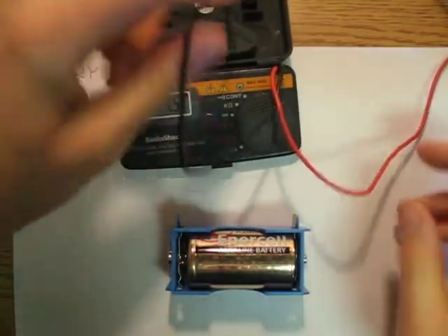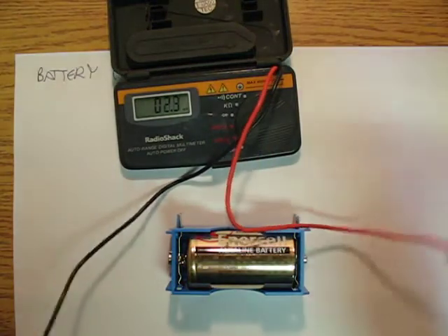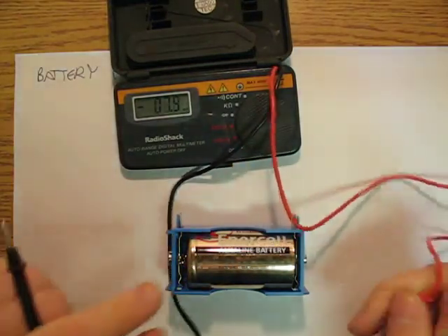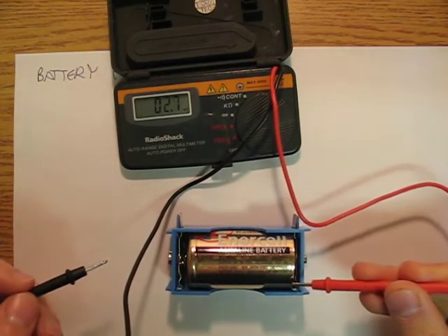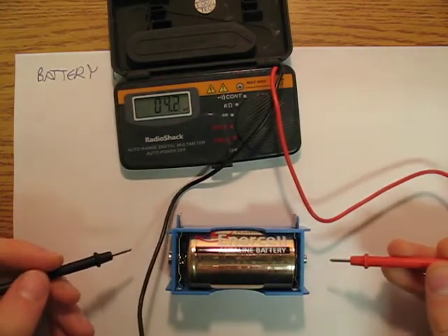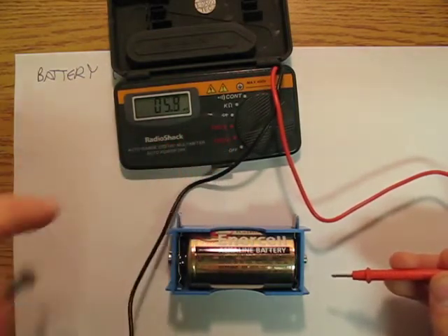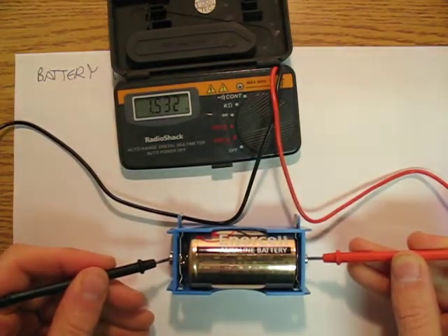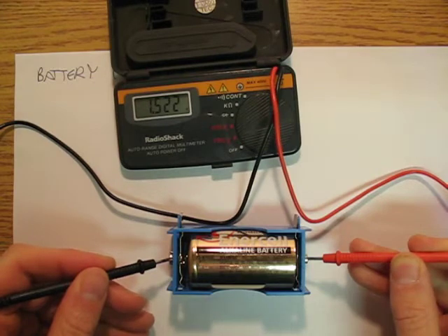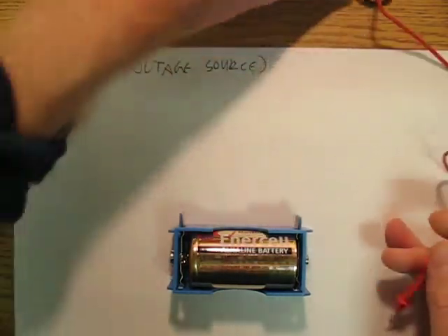And so I'm going to take my little multimeter here, and I got to identify the negative side. This is my negative side, so black goes with my negative side, red goes with my positive side, and I have my little multimeter here on DC, on volts DC, and so I'm going to plug like that, and it's going to say 1.522. So my battery is going to be 1.522 volts.